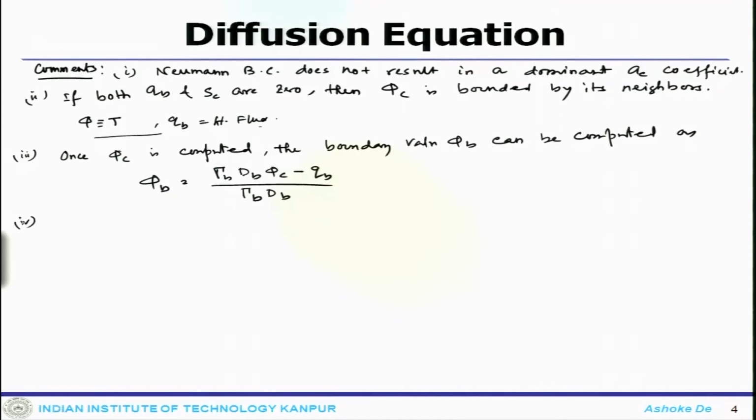And the last one is that actually this Neumann condition can be treated as natural boundary condition for finite volume method, for boundary condition for FVM, because this means whenever we are dealing with some flows or heat transfer related problem, if the flux is specified, that is quite handy to implement in finite volume method.